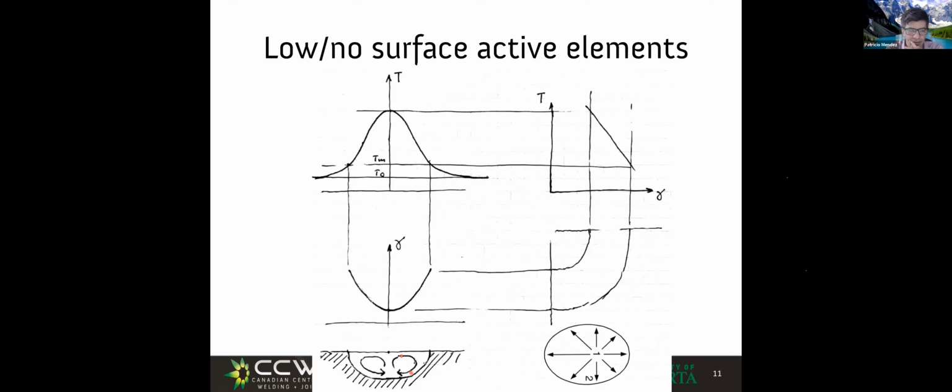What would you expect? That this is the deep weld or the shallow weld? Yeah, low penetration, exactly, that's what happened. And that's why they saw this effect in the welds with higher aluminum, because with higher aluminum, you suck up all the oxygen because aluminum is a very powerful deoxidizer, and they were having essentially a pure metal that didn't have penetration.